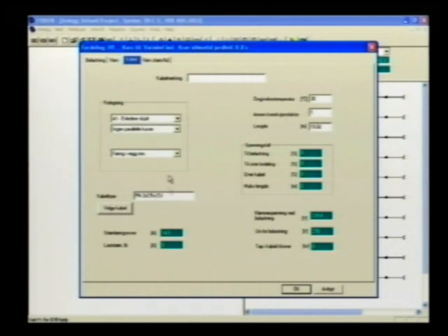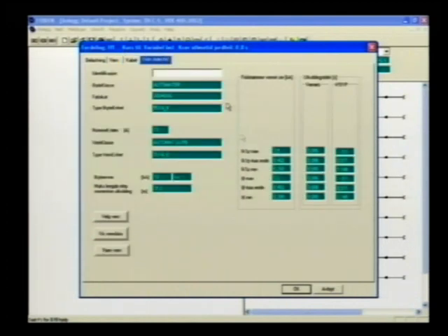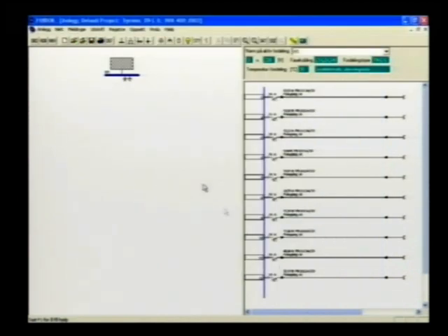So there are two things we can do. We can either reduce the nominal current of the protection device, or we can go to the cable and say that, well, we increase the cable to 2.5 square millimeters. I prefer the last one because that's better for the electricity assurance. And of course, then I go to see the protection device again, and it's okay. It's okay, and then we can just accept it.